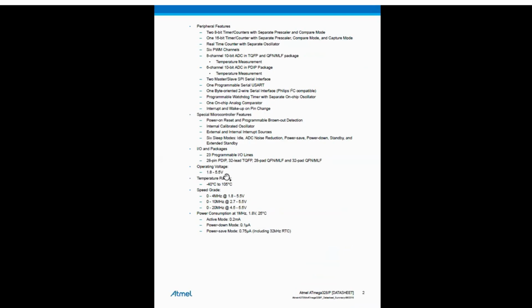That means your IC supply voltage should not exceed 5.5 volts. So when you give USB supply, it will be this. But when you give V input on the Arduino board, you can go up to 20 volts also, 18 to 20, because the Arduino board will have a regulator on top of it, a 3.3 volt regulator or 5 volt regulator, which will reduce that 20 volts to 5 volts, and it will give 5 volts to the particular Atmega 328 IC. So this is about the ICs.